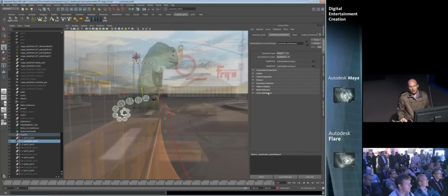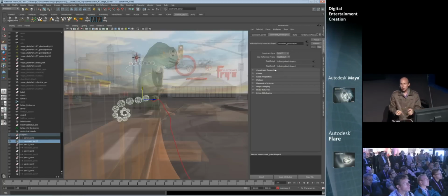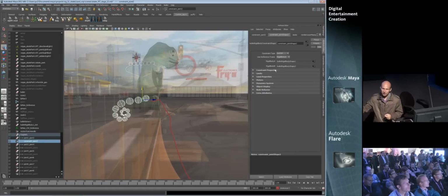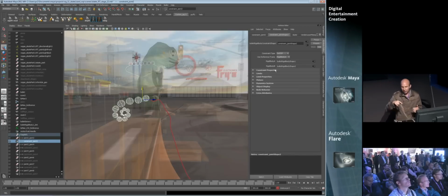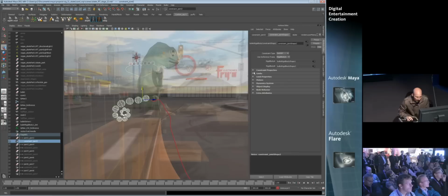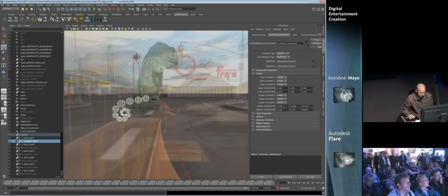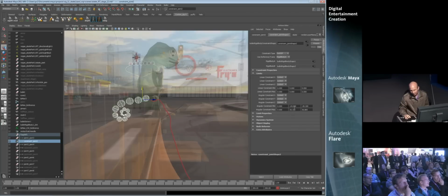The constraints are kind of smart. This obviously is set to be a 6 degree of freedom constraint. It knows to look to the joint that it was derived from to establish its rotation limit. So I wanted my tail to always maintain a nice curl or kink to it, so I set rotation limits on those joints. If I look at my limits for this selected constraint, you can see that it's been limited in X, Y, and Z, positive and negative. So min and max in X, Y, and Z have been set.